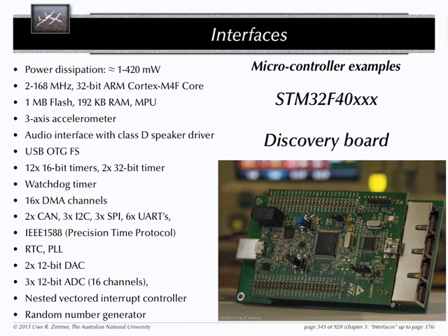Because you get a tiny bit wrong and the thing just stops. And it's very easy to crash it if you overlook a single instruction along the lines of this device interface is to be read in 16-bit instead of 8-bit. This has to be read in 32-bit, and you crash the bus and the thing crashes. That happens very, very quickly.